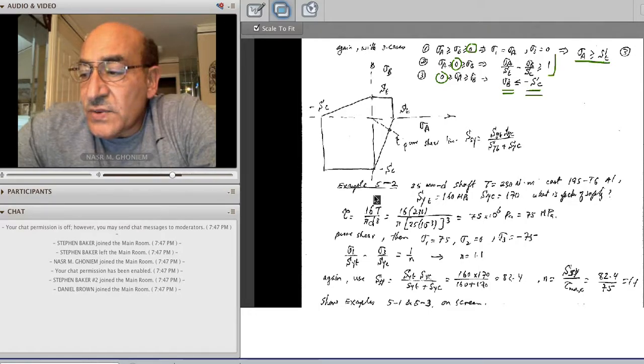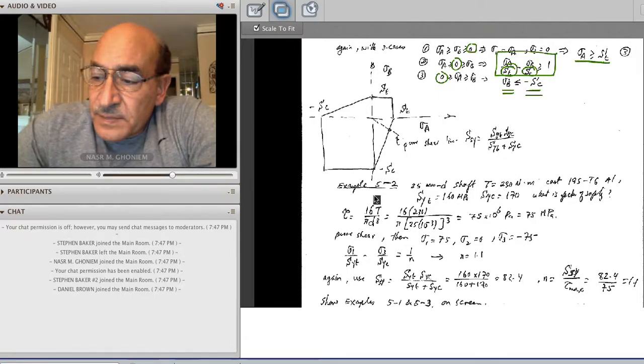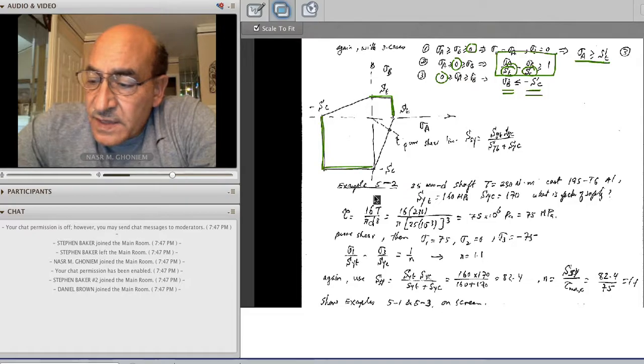But in between, you get an equation of a straight line, but it is not exactly 45 degrees because the tension and the compression strengths are different. So you end up modifying the maximum shear theory. Instead of being a box exactly, the box has one part small, one part big, and then you connect with straight lines.